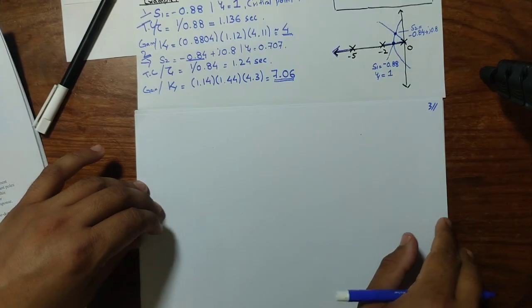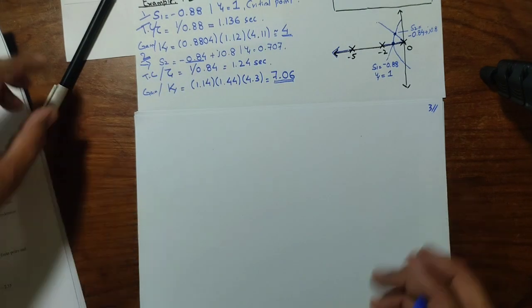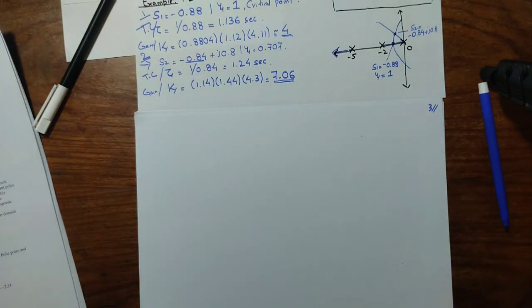But now, the actual question that has been asked of us is that we have to design a PD controller, right? If the question does not mention that we have to design the PD controller, then we can conclude from the asked criteria. If someone has asked to improve the transient performance of the system, like overshoot, settling time, time constant, rise time, peak time, then we will try to use the PD controller.